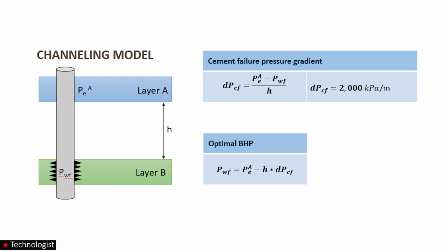As was already mentioned, my task is to calculate the critical pressures and determine production targets. To find the minimum critical bottom hole pressure, I use this formula. P is the reservoir pressure in the adjacent water-bearing formation, PWF is our desired downhole pressure, and H is the distance between the perforated and non-perforated layers. Delta P is the average pressure variation at each meter. The final formula is shown here. Using this formula, we can calculate the downhole pressure.